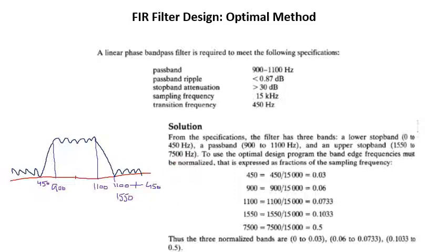You understand the relationship between the linear frequency and the angular frequency. We write omega for the angular frequency. Let me write the continuous time case: in continuous time, omega equals 2 pi f. Similarly, for the discrete time case, it will be 2 pi f divided by the sampling frequency. So we can obtain the angular frequency, or we can also obtain the discrete or normalized frequency in terms of linear frequency.